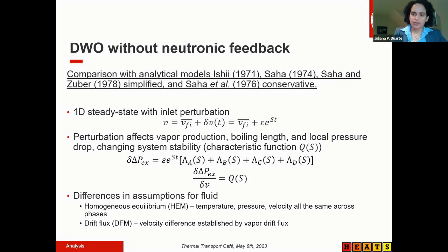So it goes back to the idea that at some point we have this negative feedback from the friction part that is going to lead the mass flow rate to grow, and lead to an unstable condition. There are other, more simplified models in the literature that we also used, but it was more to compare some parametric effects of some parameters in this model, which we are not going to talk about today.